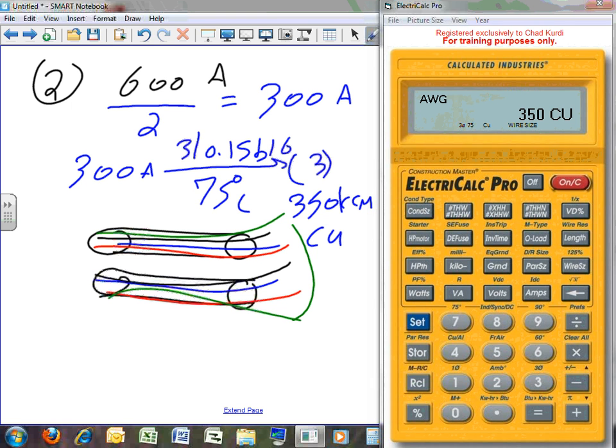At the end, you tie these 2 together to the same lug. In both ends, tie these 2 together, and tie the blue together, and don't forget to tie the black together on both ends. So the other end here, where's my black here? Here you go, tie together, same lugs, and then you take the blue again, the blue with the blue, and the red with the red. And again, they're tied through lugs, guys, and the green with the green. The green in both ends with the green. That's what paralleling is all about. You tie them at the end, at both ends of the cable.